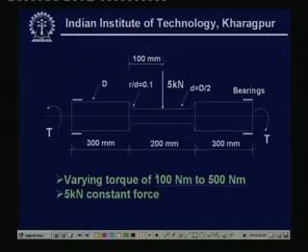Now, you can see this is simply a fluctuating stress. So, we can find in a similar manner the stress amplitude, which we will call the shear stress amplitude, and the mean shear stress, and carry out the calculations taking ideas from our previous design calculations. Let us assume, just to cut short all the other calculations, that the size factor, surface factor, and temperature factor remain the same for this particular problem also.